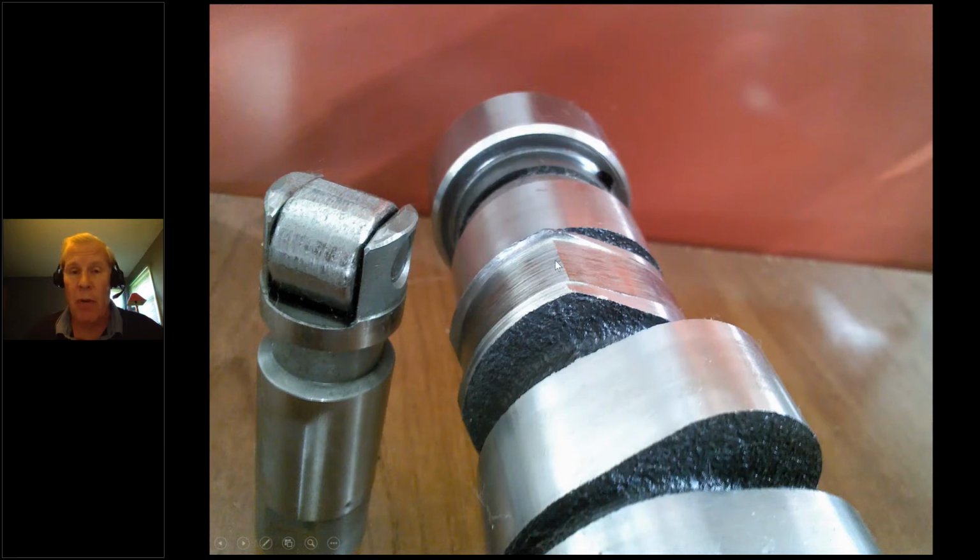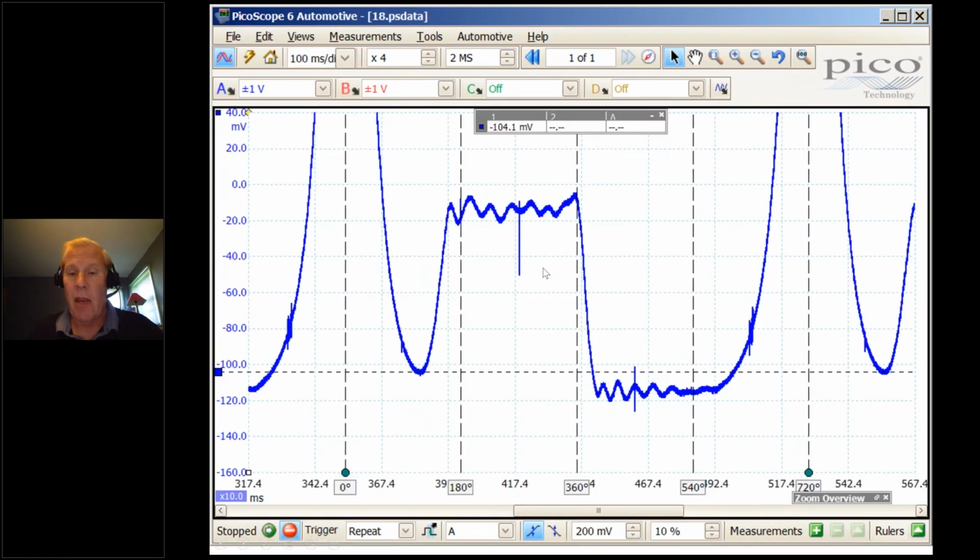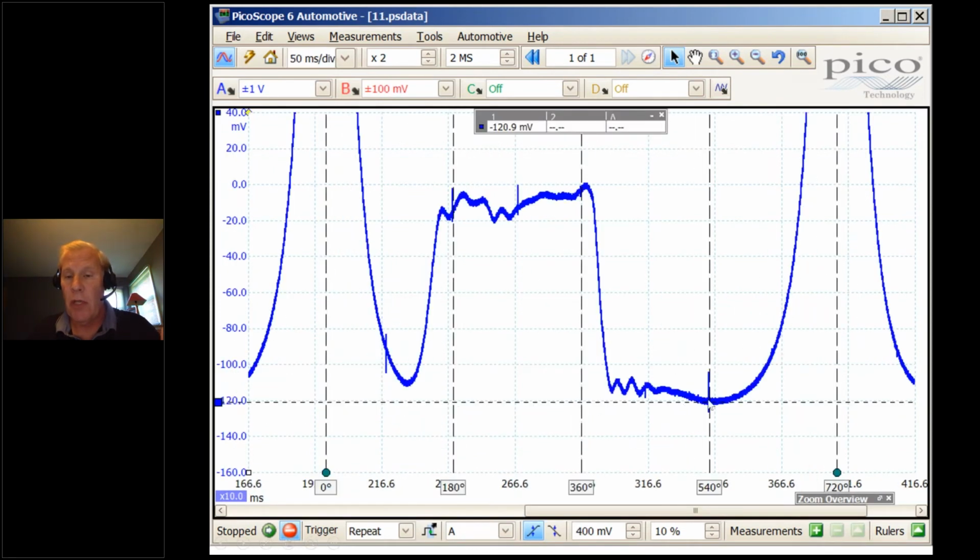And I've seen a number of these Hemi engines, without trying to be a pattern failure technician, that have worn intake lobes. And they're sometimes difficult to diagnose because they don't really show up at idle. You have to force more air into the engine. But I guess I'm going to summarize by saying that if a tech knows what to look for, you can see the subtle clue where the intake valve closed way early and we pulled deeper in the vacuum. So that depth is not because of the throttle blade, it's because of the restriction into the intake.